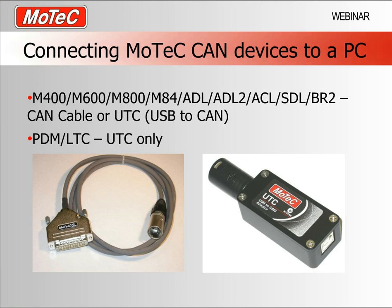You'll see that the one on the left, which we call a CAN cable, uses a printer port, which is in fact almost redundant now on most PCs. So the device we most normally would use is the one on the right, which is called a UTC, which is a USB to CAN converter. Now, most of our MoTec controllers or devices will communicate via either of these cables. However, some of our later products will only communicate with the UTC. So most of our ECUs and dashboards can be used with either type of cable.